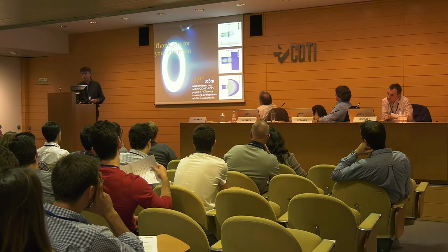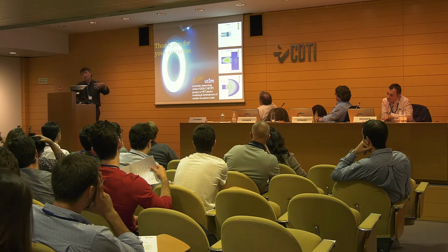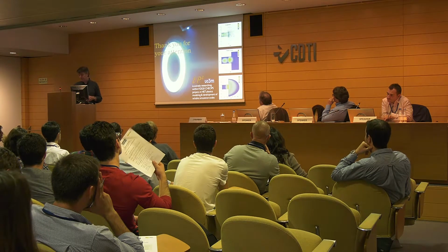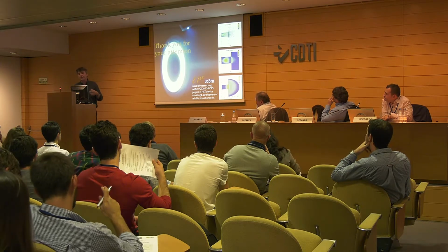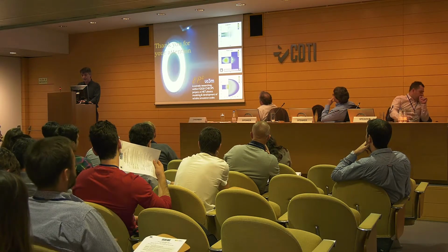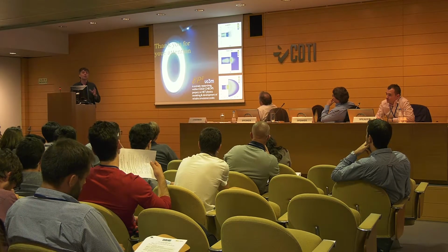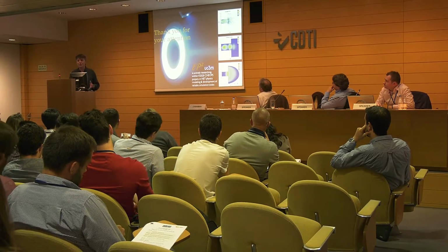What you are seeing here are what are called hybrid codes. These are ion particles, so we have around 1 million ion particles and 1 million neutral particles. We move them, we model all the collisional processes to create the plasma, and then from these particles we extract average magnitudes like this, which would be the ion density in the thruster chamber. So these are the tools we are developing, but we need more physics, and you are most welcome to help us do that.